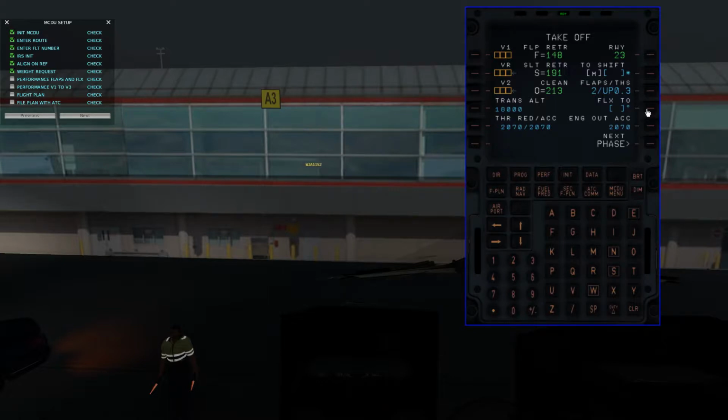The temperature flux, I'm not really sure. I haven't really studied what the correct procedure is for setting that. Someone said you'd take the current temperature, add 32 degrees. Whether that's correct or not, I don't know. But anyhow, putting in 48 works. Then for the VRs here, you can actually click on them and it'll put in the correct VR takeoff rotation speeds. And VR1 you need to input manually, so we'll just put in 120.